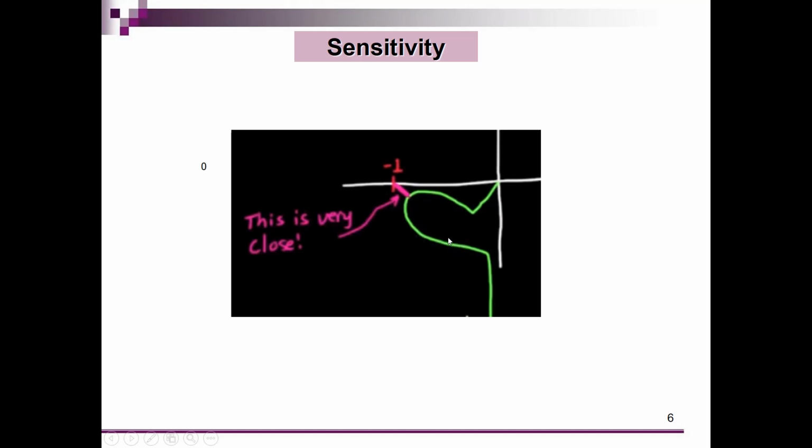But what happens when you have this kind of a Nyquist plot, that at this frequency, the distance between the Nyquist plot and the point minus 1 will become very small. So the sensitivity, which is 1 over this distance, will be very high. But this is not what we want. This is very close. So this could be when you have tolerances causing a problem. So we want to have a margin on that distance. And just like the gain margin, we often define a gain margin of 2. We also define a sensitivity margin in order to make sure that this distance is not too small.